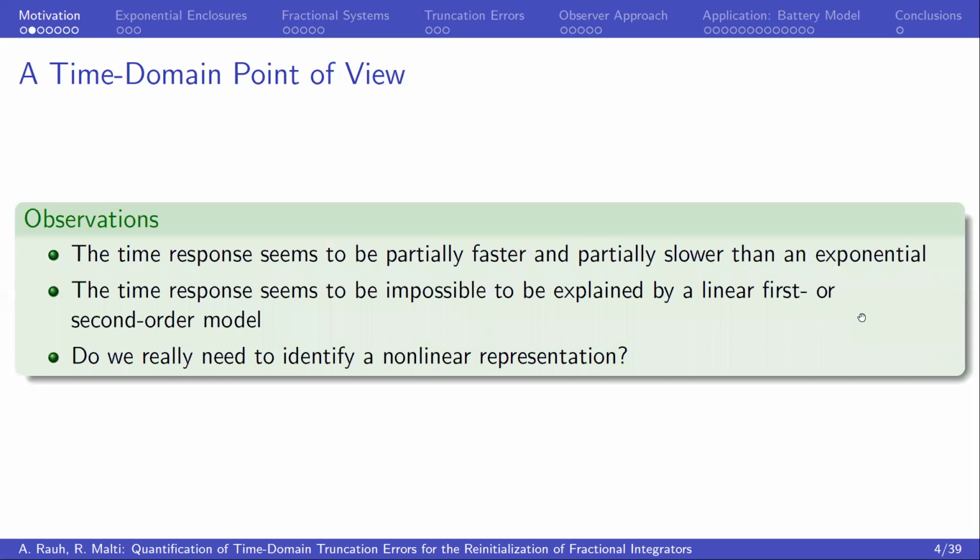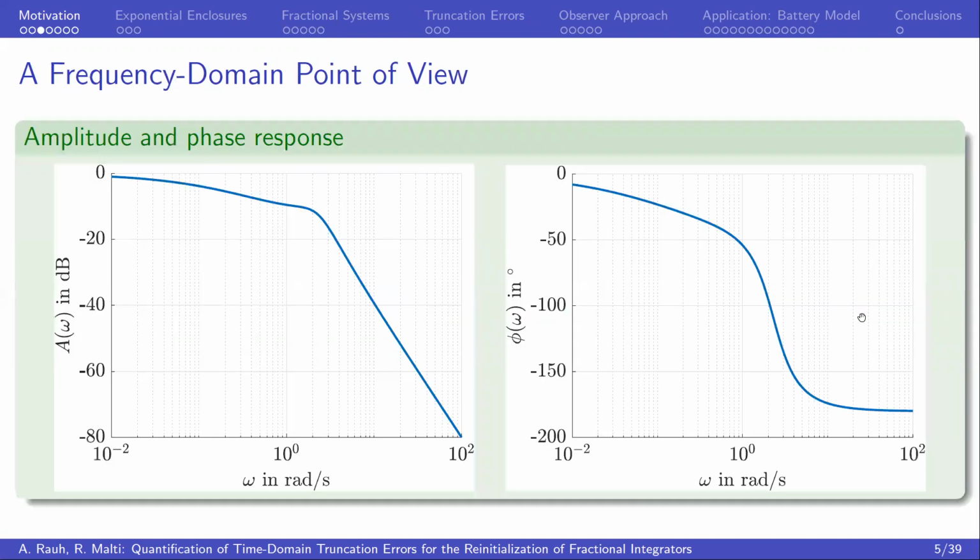function. Moreover, the question arises: is it possible to explain the corresponding dynamics by a linear system model of low order, for example, a linear first or second order state space representation? Or is it really necessary to identify some nonlinear system representation? Before we come to an answer to these questions, we take again exactly the same system model and record the corresponding frequency domain responses. On the left-hand side, the amplitude response. On the right-hand side, the corresponding phase response.